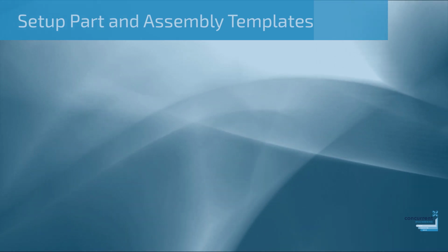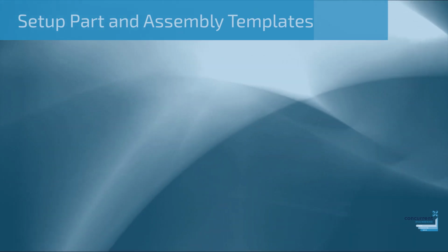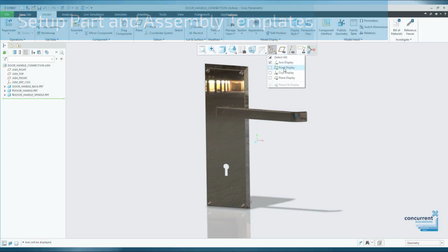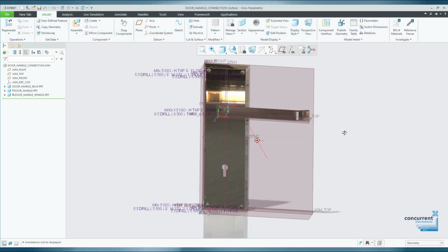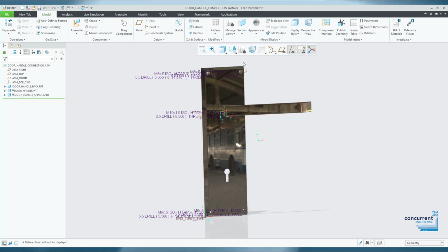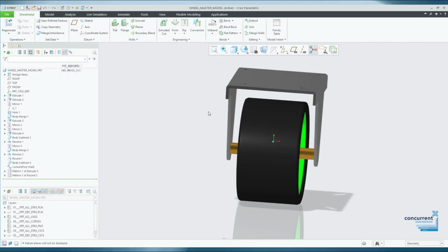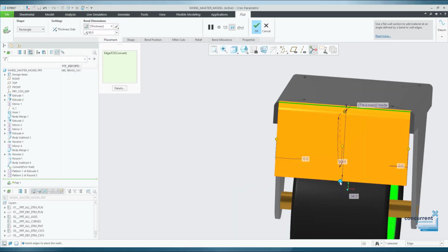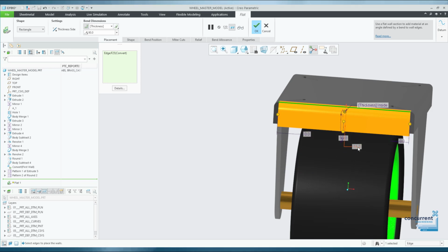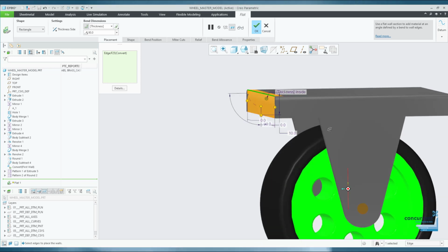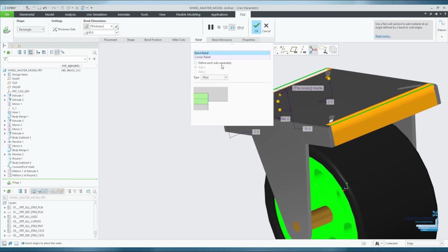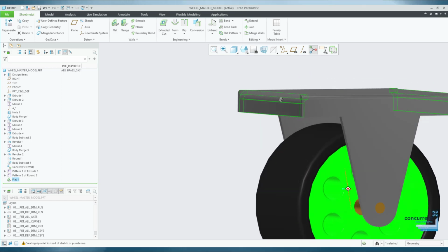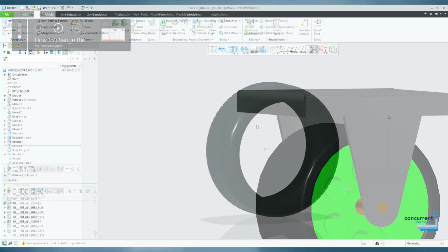By default, Creo includes a series of templates for parts, assemblies, sheet metal, ECAD items, drawings, etc. Now these are essentially a preset series of pre-configured items, for example units, datums, layers. The default units in the part, sheet metal and assembly techniques are imperial units, i.e. inches and pounds. However, most of our customers in the UK and Ireland will require metric units to be the default when they're measuring, inspecting and indeed designing parts.